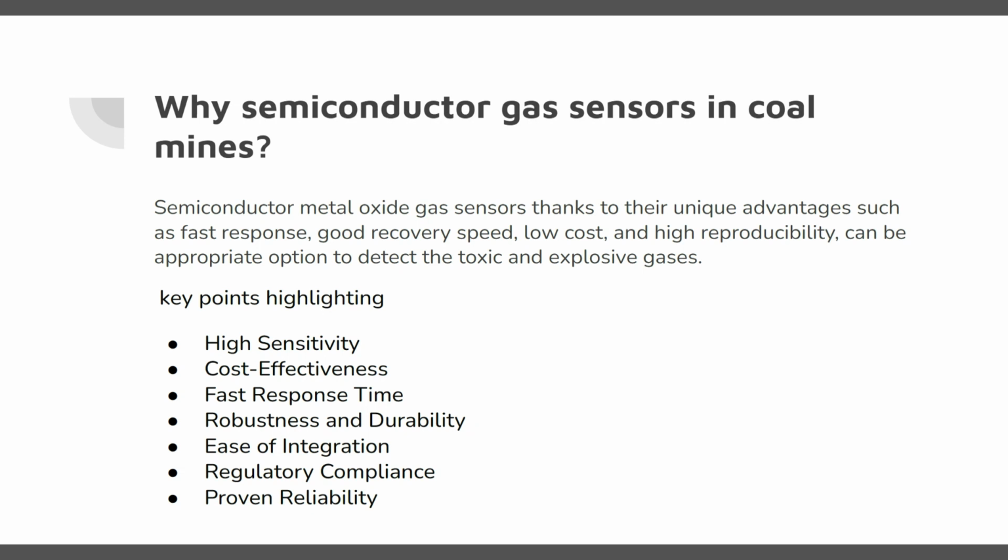So based on various factors such as those listed here, we prefer semiconductor gas sensors. Whenever we choose a gas sensor, the primary qualities we check are the amount of sensitivity we require, the selectivity towards the target gas, and its rapidness.